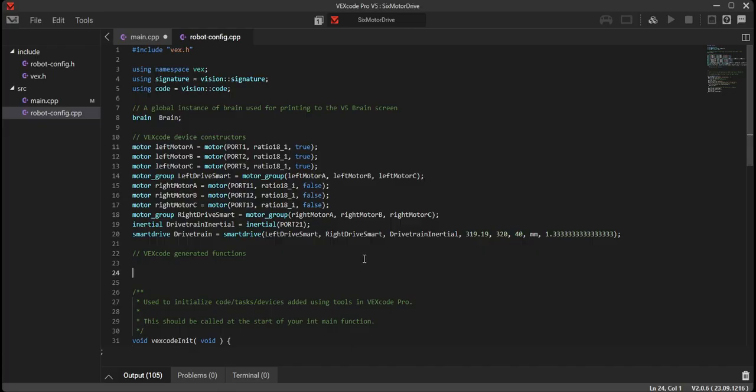And now we have a 6-motor drive that should otherwise have all of the same functionality as the built-in 4-motor drive. A good way to test this is to first lift your robot up so the wheels aren't touching the ground, and then I would recommend unplugging all of the ports except one at a time.